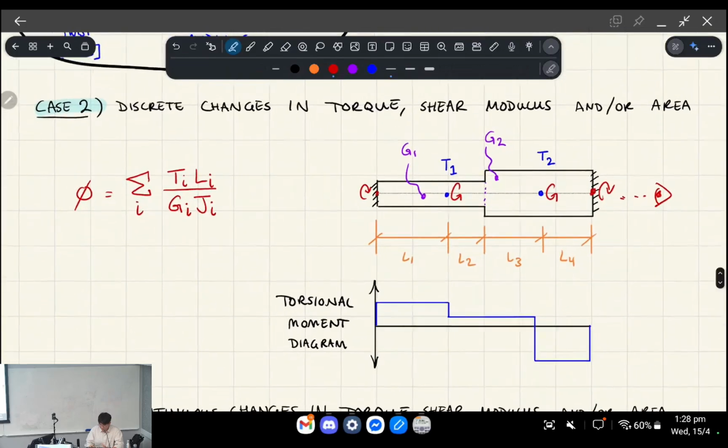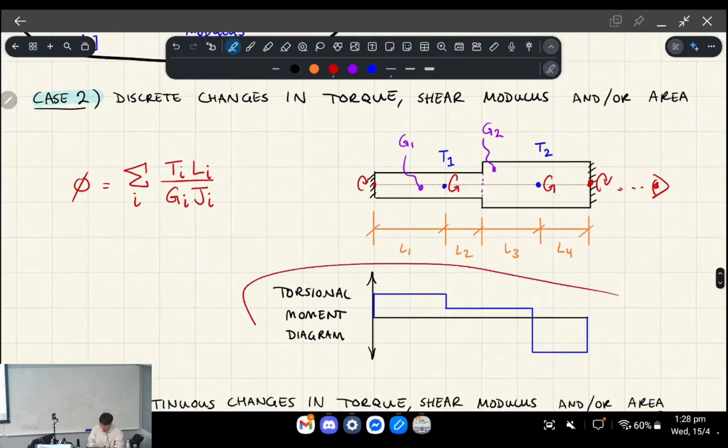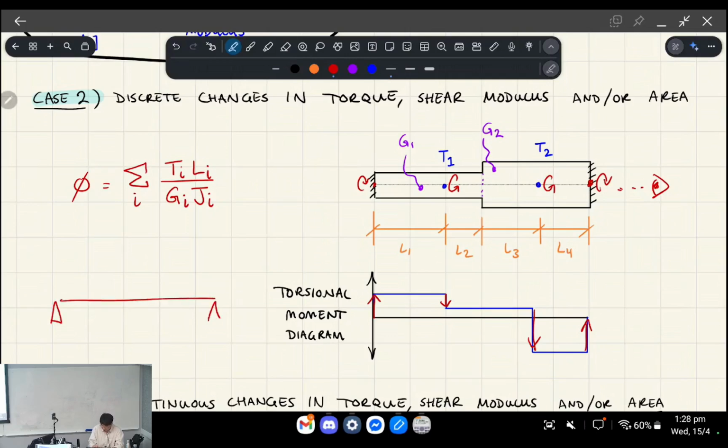So what I'm trying to tell you is if you think about a torque moment diagram, and I map it going left to right, whenever you have a clockwise moment, it actually brings you up in the torque moment diagram. So that jumps up. And whenever you have a counterclockwise one, it goes down, okay? So you might think this is a little bit unintuitive and different to the direction of shear force, V. But it's actually the same as if you had point moments on a beam.